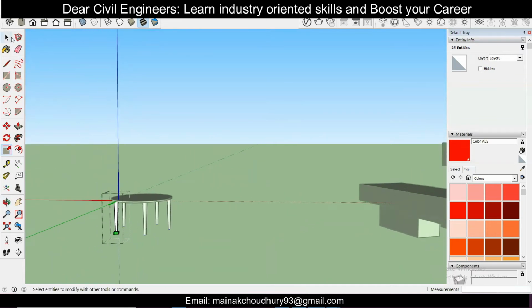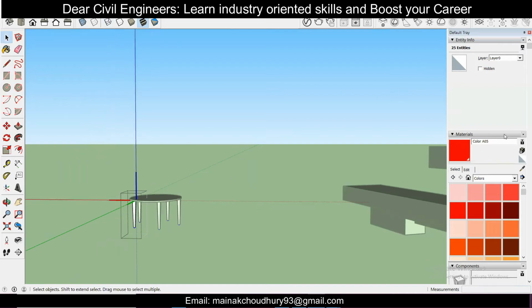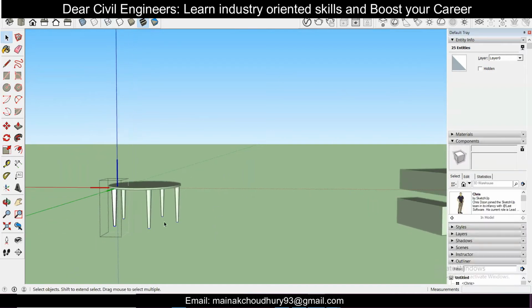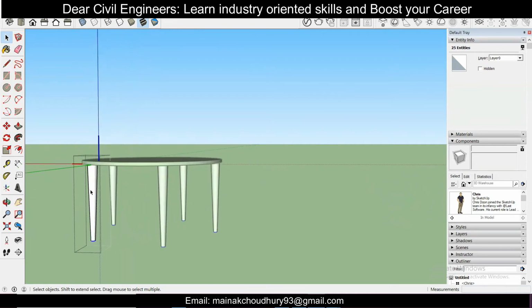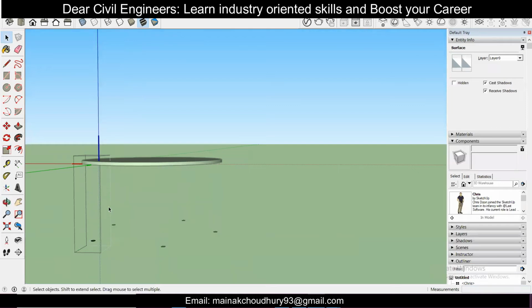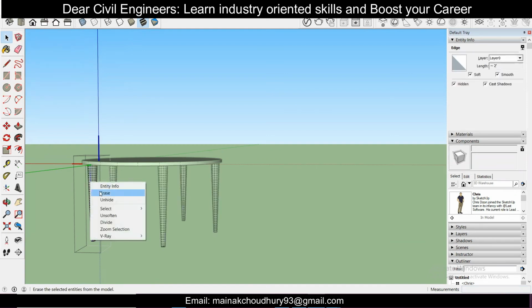So let's focus on some more options here. So here you have the window materials. Just close it for now. And in this components option, there is an option of hide. So let's see. You can right click and then click on hide, then it will be hidden. If you want to view this, go to view and then select hidden geometry, and then you can click and then unhide.